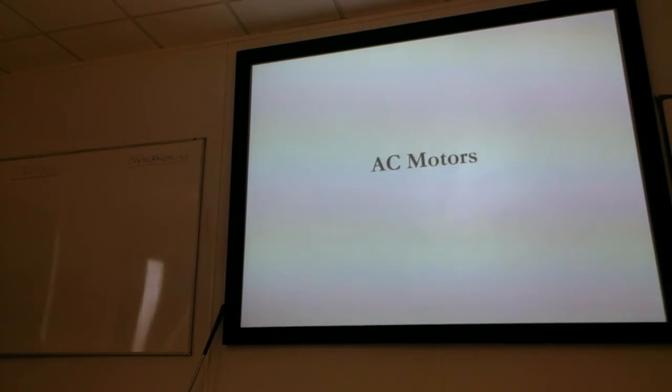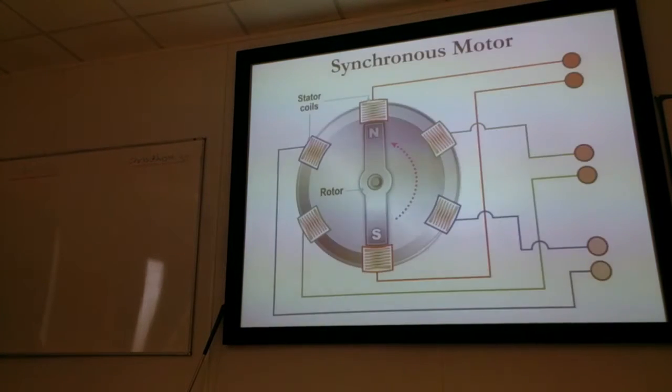AC motors. Okay. Synchronous motor, look familiar? It should do. It's the same as a three-phase AC generator. Also called a synchronous motor. Relatively low torque, good for constant speed applications. Might be single phase, this one's three phase, and they're not self-starting, or they're not self-exciting.